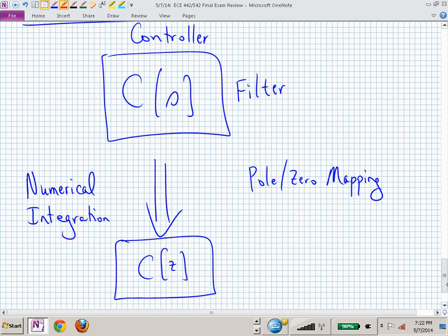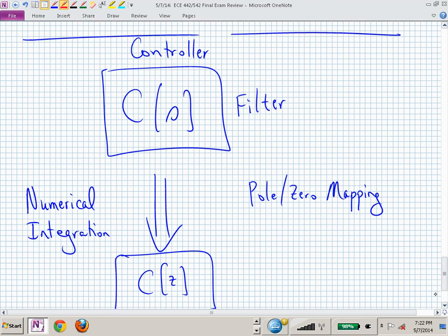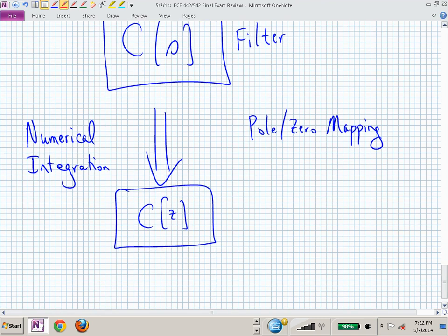Versus down here, now what does T depend on? Here it may depend on the signals that you're filtering. You may be low-pass filtering a bunch of noisy or high-frequency content signals. So T may have a different reason for its value here versus in the zero-order hold equivalent. If it's a controller, then it's probably based on your closed-loop dynamics again. So what you use for T is going to be important, and there's some justification behind it.